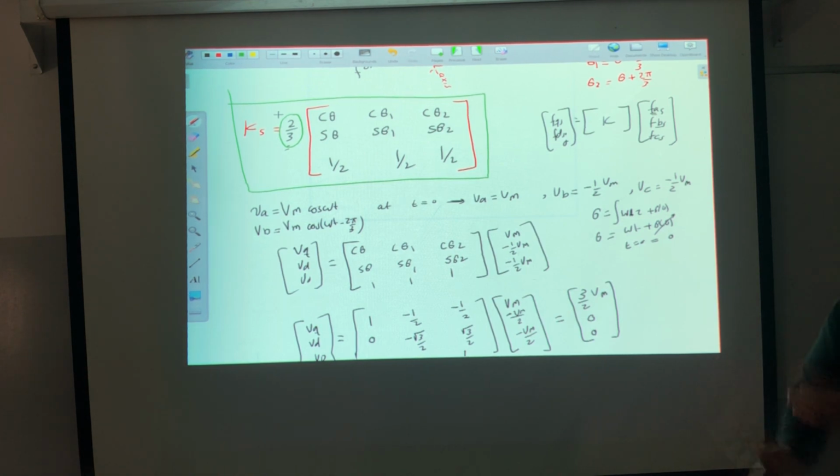Because if you are solving your problem in the Q and D reference frame, in the end of the day the inverter cannot understand the Q and the D. The machine cannot understand the Q and the D. The machine understands the ABC. You can say 3 terminals: A, B, C, the 3 phases, called line 1, line 2, line 3, called R, S, T, or XYZ, whatever you want. It's the machine variable, the ABC.